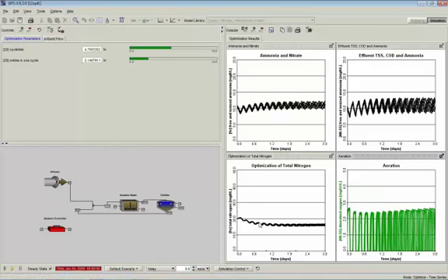And so we've now converged to a final answer. If you remember before, we were way up here with a total nitrogen in the effluent of about 25, and now it's saying the best combination that the gpsx optimizer could find is at about 17. So this is the optimal setting. It's saying that for every 4.75 hours, we want the air on for 2.14 hours. So that's obviously pretty precise. It's done it in a completely mathematical format here, but that's the idea behind using it for a process optimization.